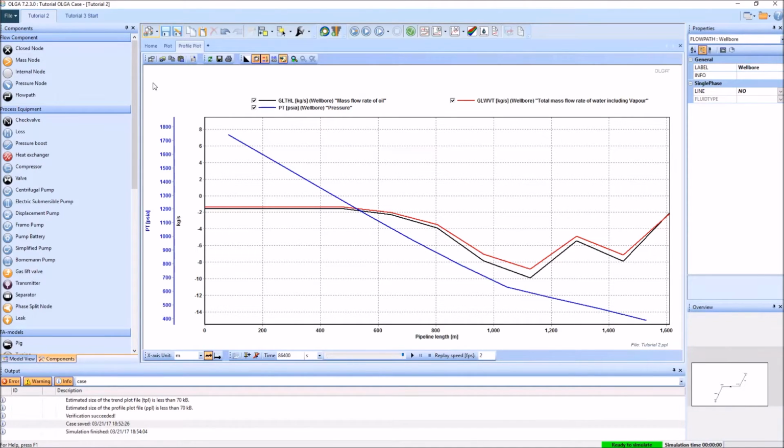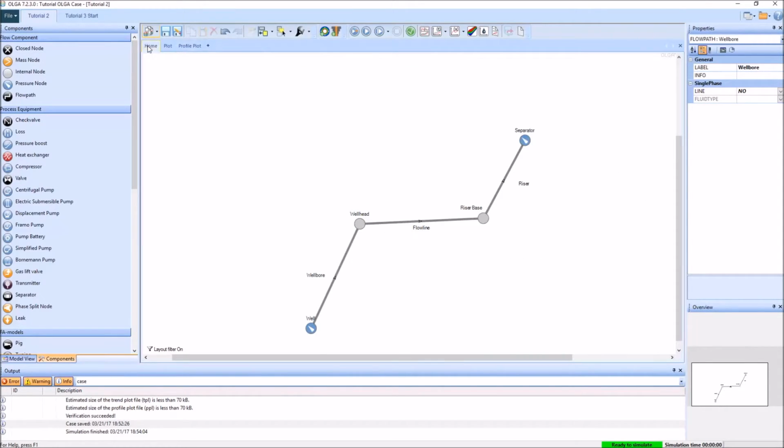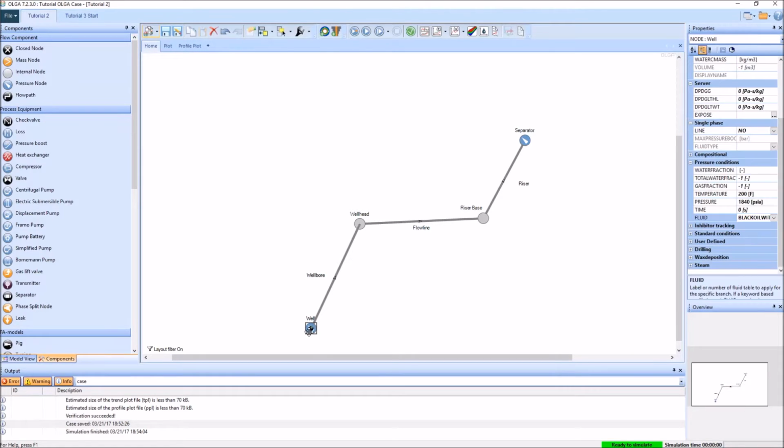So what this means in practice is that if we want to get forwards flow and actually produce some oil, then we have to bump up the pressure that we have available at the inlet. And so this is just sort of a lesson in the requirements of static head to actually get this thing to work properly. Let's change our inlet pressure up to 2000 psi, and we'll run that case once more.